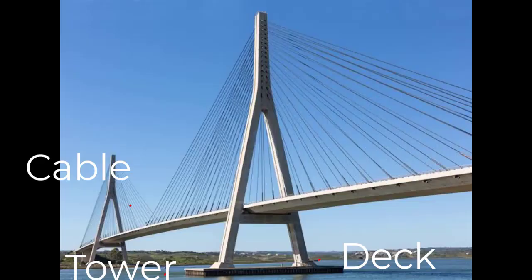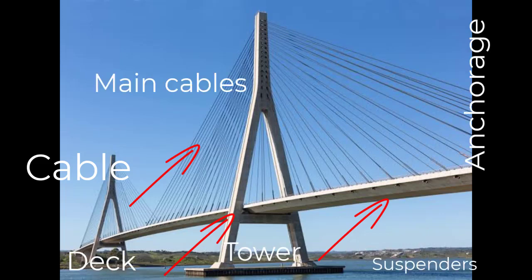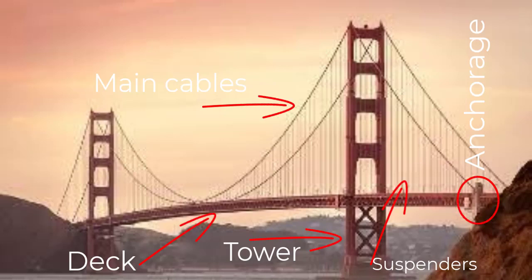The number one difference is the orientation. In a cable stayed bridge, we have a long tower at the midspan of the deck. Then we have cables running from the tower and connected to the sides of the deck. But in a suspension bridge, we also have a long tower at the midspan of the road deck. Then we have a main cable that is running in a saggy pattern from one tower to another tower, or from one tower to an anchor.